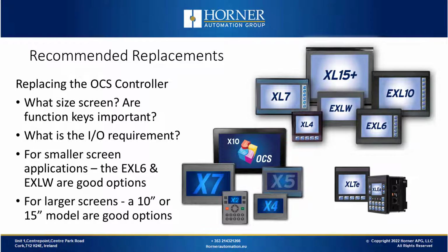Now let's look at some modern replacements that you can use for some of these older systems. There's no one right answer here, but here are the factors that you would consider. You should ask yourself, what size is the screen you're replacing, and are the function keys used in this application, and if they were, do you want to maintain that? You also need to ask, what is the I/O requirement? But again, if you're not really sure, for smaller screen applications, the EXL6 and the EXLW are good options. For larger units, a 10 or a 15 are good options.